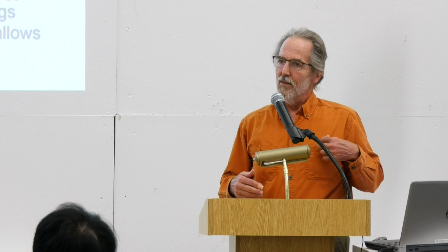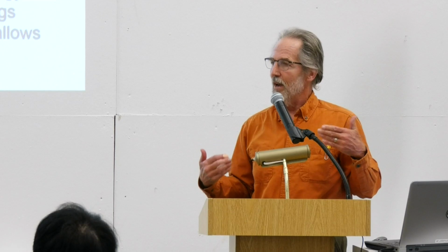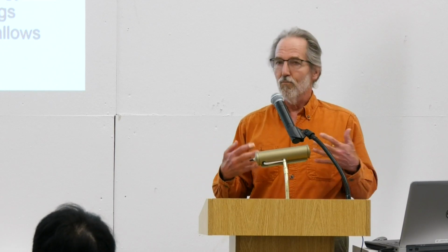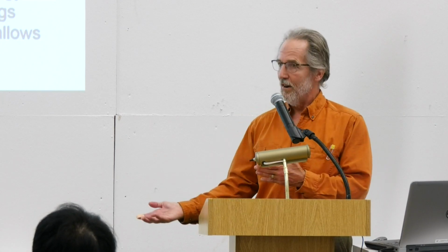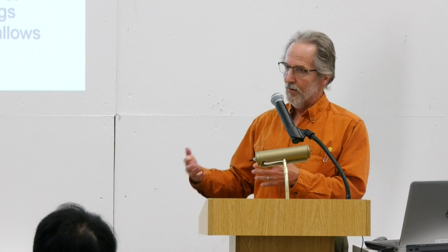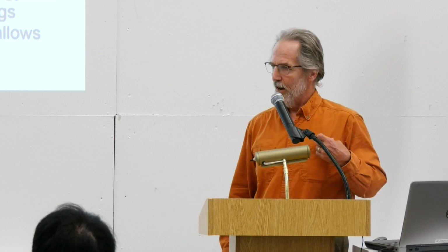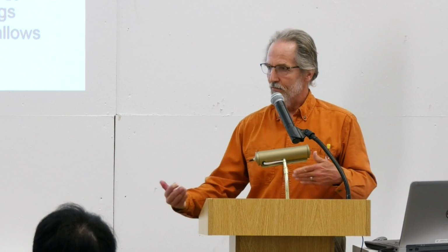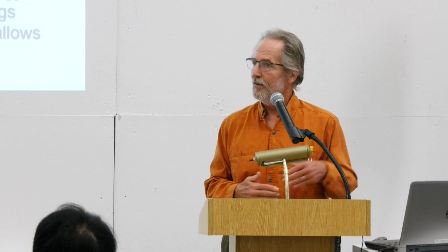So what that tells us is that we're trying to get to zero over the course of a year. The solar panels are going to produce more energy in the summer, like May, June, July. So to really get to zero, in most cases, you're looking at producing more energy than the building needs in the summer. And then likely you won't be able to completely produce enough energy in the winter to run the building. But if you look at a year's worth of energy, the surplus that you generate in the summer is going to balance out the shortcoming in the winter.